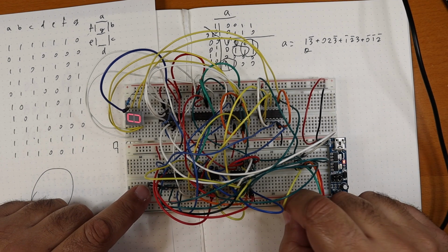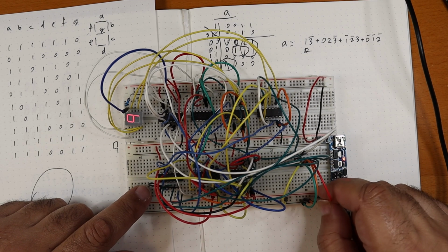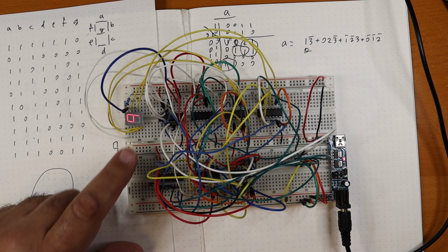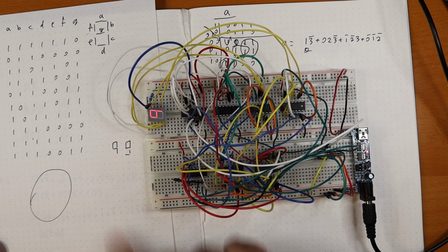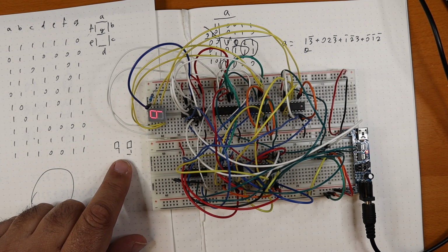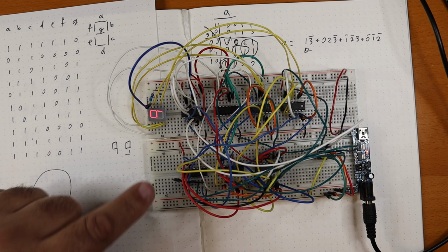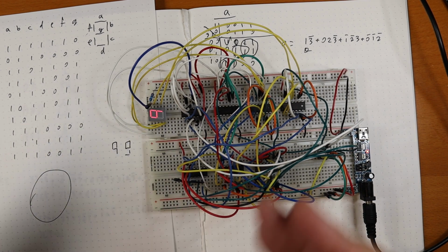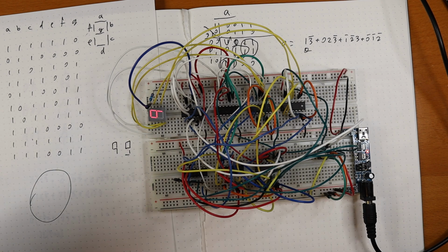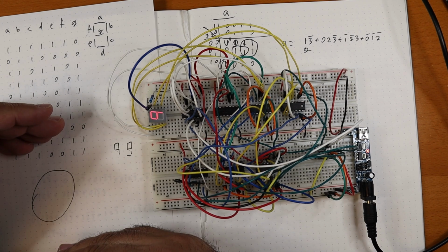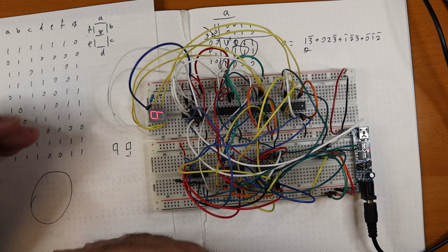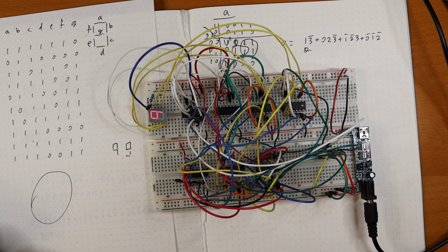The first hint is what happens when I want to encode a 9. You'll notice that I specifically get the version without the leg. Why? Because it would require more logic gates in order to get the version with the leg, so I chose the one without. Which pretty much begins to tell you what I'm doing here. I'm adapting the requirements. I have some leeway within the requirements, and I'm using the leeway in order to take something that satisfies the requirements, however, does so in a way that it uses less gates.